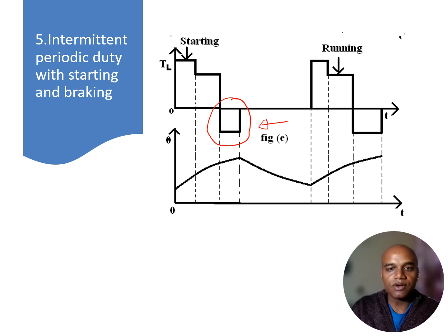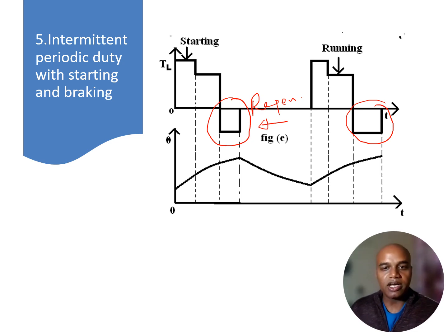Here we are talking about regenerative braking. Similarly, here we also have a torque requirement which is opposite to my speed, so this is nothing but the braking period. And if we correlate with the four quadrant operation of the drives, then we can easily understand that this requires the second quadrant, and the second and fourth quadrant, based on whether my EV is going in the forward direction or in the reverse direction.